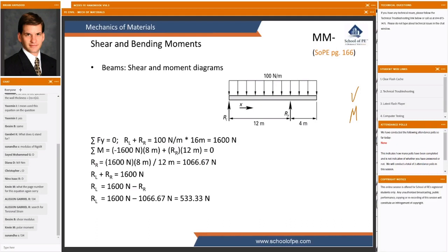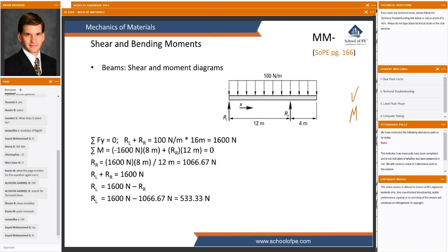As we learned in statics, to find the reaction forces, we might ask two questions to keep us headed down the right path. Is this problem symmetrical? In this case, the loading is symmetrical, but the supports are not symmetrical. So we'll say, no, it's not symmetrical. And then we can ask, which reaction force is greater, the left one or the right one? Looks like the right-hand reaction force would be the greater of the two. So let's make sure that our answers coincide with that.